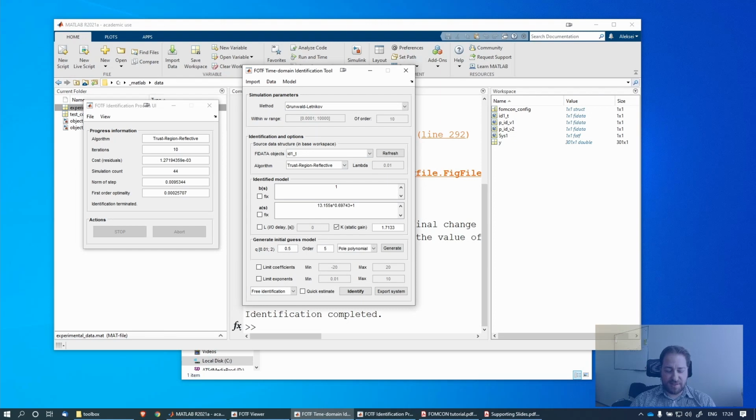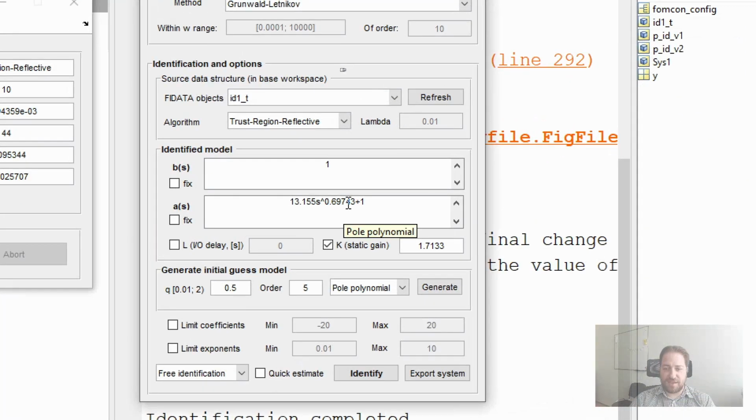But now there's a bit of a problem with this model, and specifically you can see the order, well, maybe not so clearly, let me again zoom in. So the order of the model is 0.69743. This is not very good for fractional systems. We want to keep things tidy. So at the expense of a bit of accuracy, perhaps, we will trim this one. So you can just trim this out, but then we need to correct the model so that it could take that one into account.